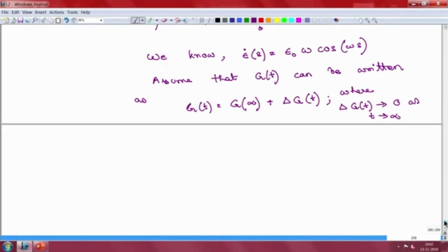Okay. So, you can see that this particular form, if you put g infinity equal to 0, then basically you are modeling a viscoelastic fluid, and if g infinity is non-zero, then you are essentially modeling a viscoelastic solid. So, you can tweak what g infinity is. You can keep it as 0 or you can keep it as non-zero, and that is not a problem. But for the time being, we are going to assume that this is a non-zero quantity.